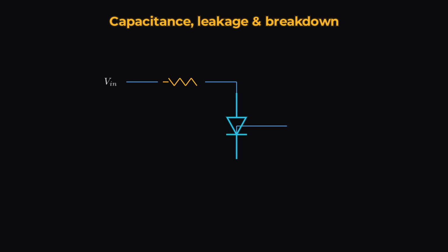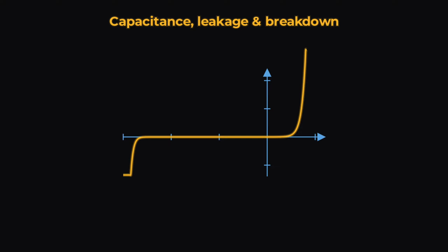Breakdown is non-destructive if the current is limited. The junction survives as long as the external circuit caps the current. This controlled breakdown is exactly how a Zener voltage reference works. We have now described the full current-voltage behavior, forward and reverse. The last step is to see where this one structure is used. This leads directly to applications.